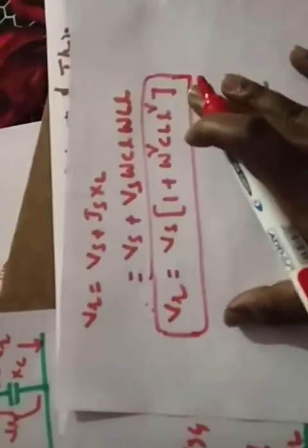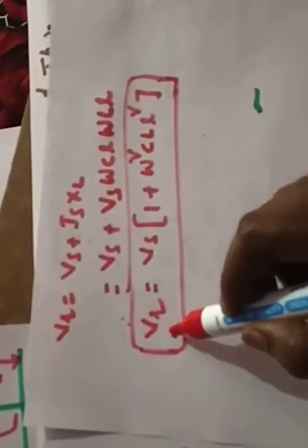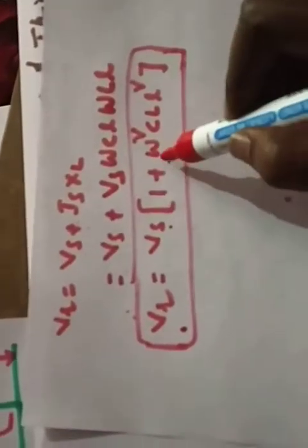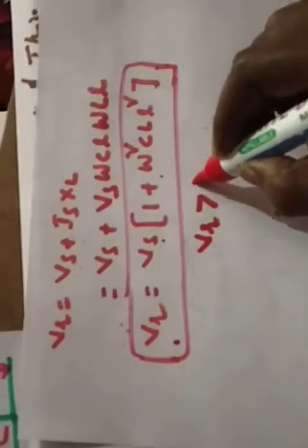So from here you will see whatever my receiving end voltage is greater than Vs plus something. So that we can call it as a receiving end voltage VR which is greater than the Vs. So VR is equal to Vs plus something value, right? So that means VR value will be greater than the Vs value. Your statement is true now. Whatever the Ferranti said, that statement is absolutely perfect. I hope it's clear. Nothing is there. Just KVL applied, right? So for a mathematical representation, we did all these things, right?